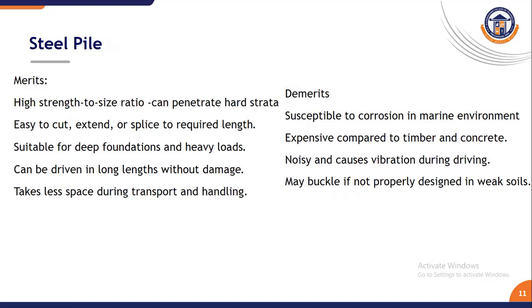And then steel pile has a higher strength to size ratio, which allows them to penetrate hard soil and rock layers without difficulty. Okay, they are easy to cut, extend, and splice, making them ideal for deep foundations requiring long piles. Okay, however these are expensive, which is a demerit.